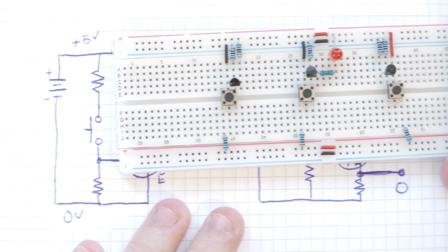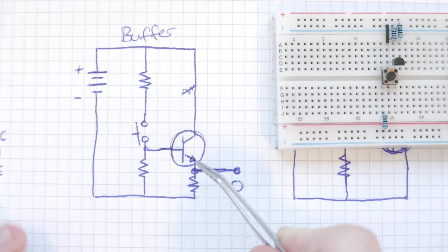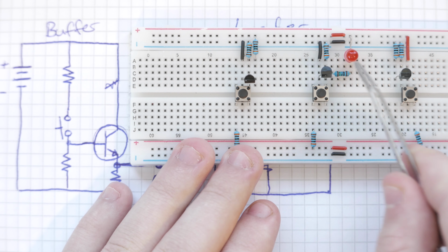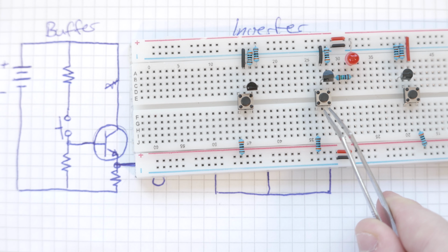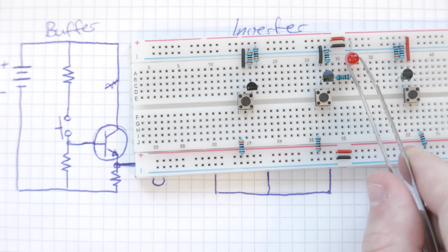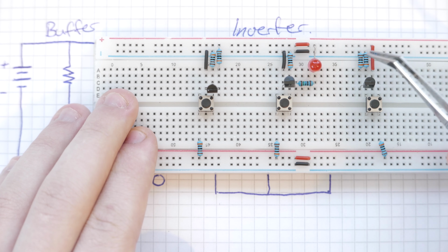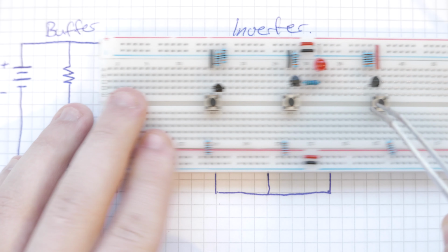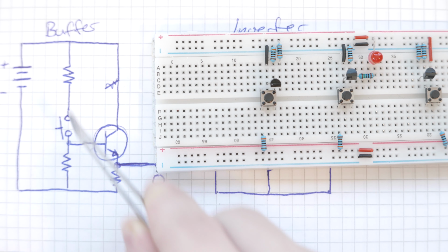Great! Now this next circuit I'm going to show you is pretty much the same, but it's something that we can actually use for signal. So we don't want to use this for logic because quite a large current flows. 20 milliamps is actually quite a lot. So we can make that lower by only using a signal that is a lot less, if that makes any sense. So here I have a 3K resistor hooked up that goes to ground, and this is 3K and this is 3K. They're all 3K, and there's no specific reason for it, except that it just works.